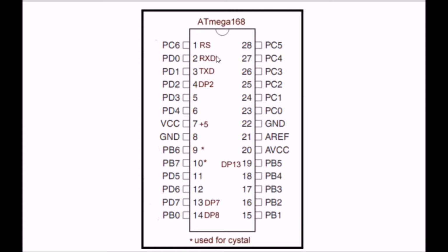You can if you want to give that up. Your next port, of course, is port C, which consists of PC0 through PC6. PC6 is used as your reset, but PC0 through 5 are your analog inputs. They can also be programmed as outputs.